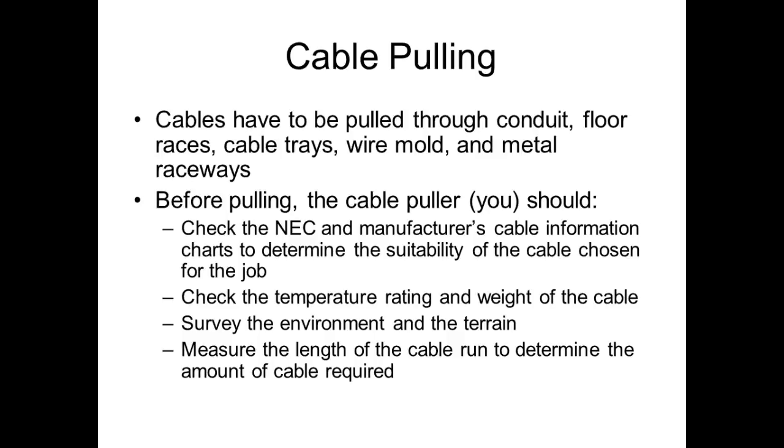Before pulling the cable, you should check the NEC manufacturer's cable information chart to determine the suitability of the cable chosen for the job. Check the temperature rating and the weight of the cable, survey the environment and the terrain, and measure the length of the cable run to determine the amount of cable required. That's awful. This happened to me.